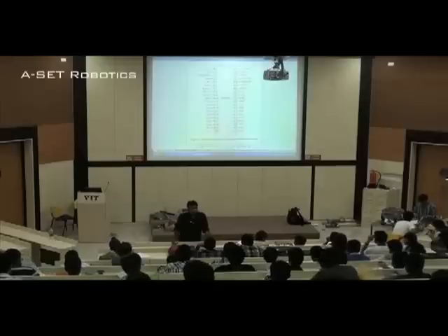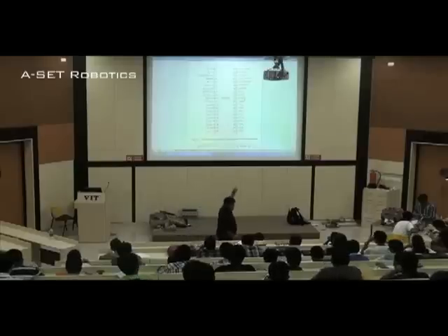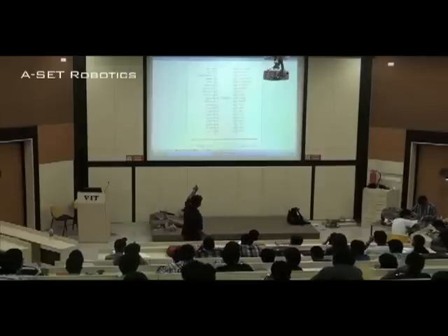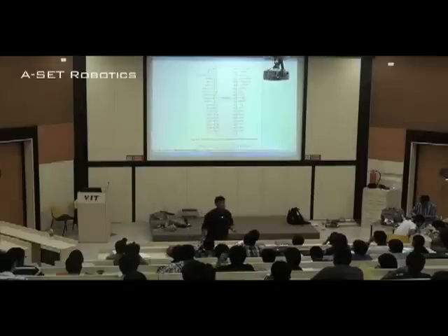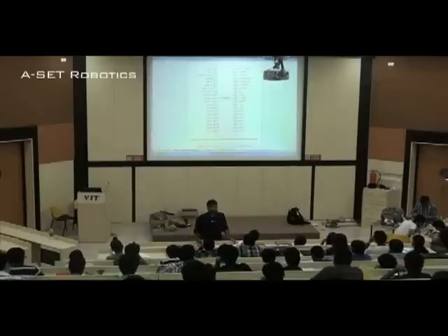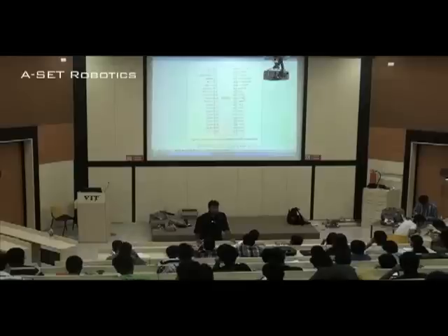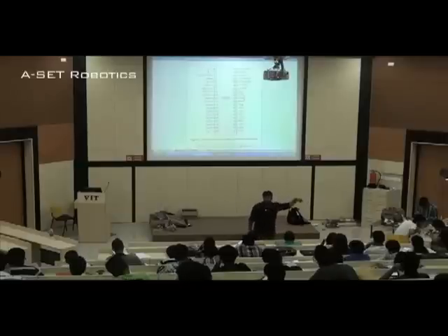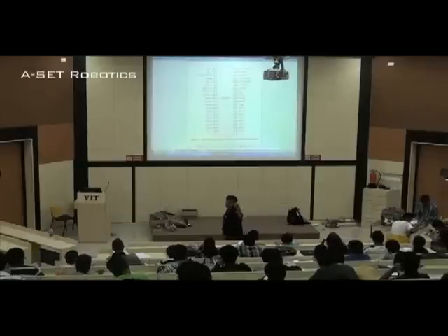Now what it does is, if ALE is high, that means that address is being transferred from AD0 to AD7. If ALE is low, data is being transferred.